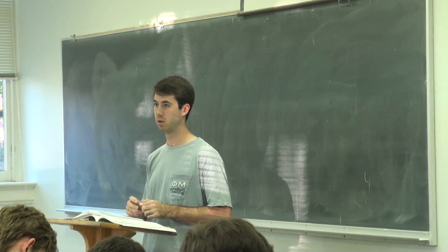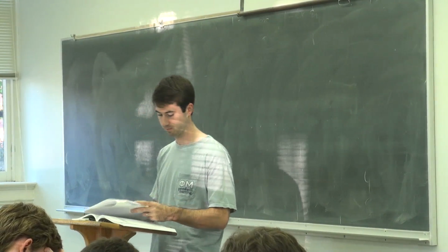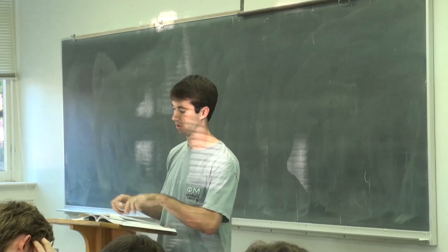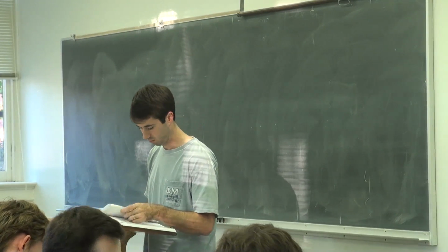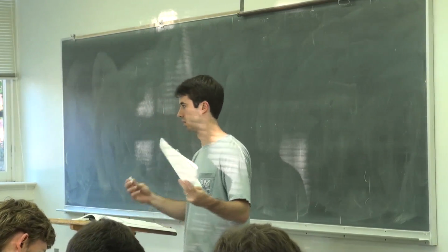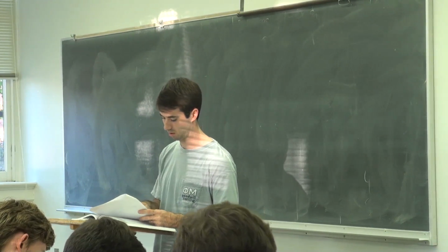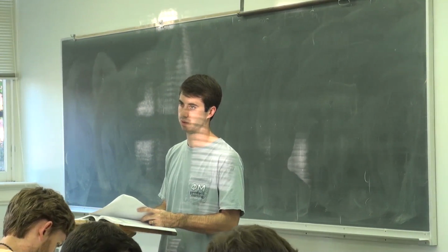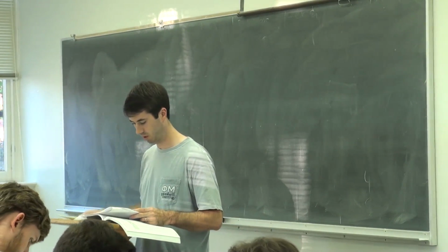What you asked for? Oh, no, I was looking for the layer coefficient, the A term, using the modulus. 0.43 or something. Yeah, so that'll work. We'll just call it 0.44, just to stick with the typical value. But they'll have stuff similar to this, where you just got to go look at the values and use stuff like that. What about for the base and subbase?